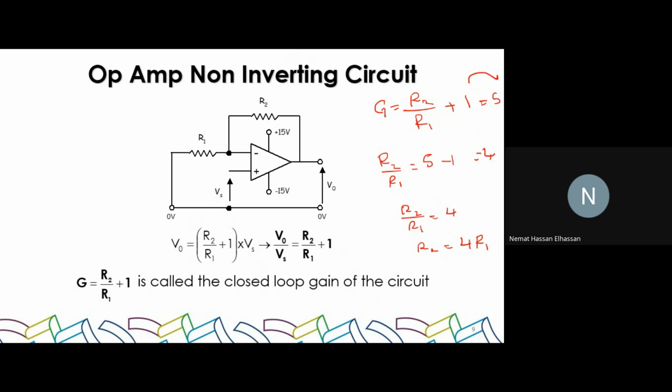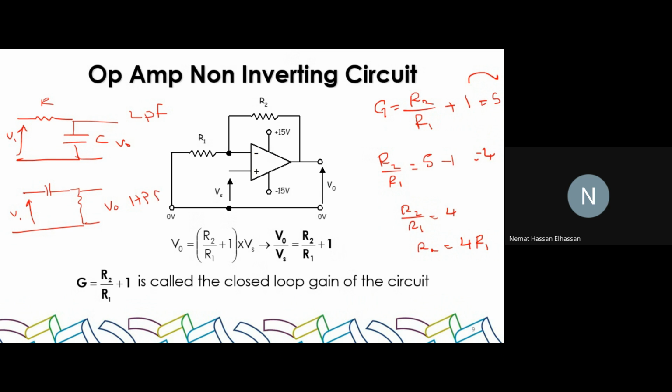Okay, I know that some of you didn't attend last week, so it will be difficult for them to pick up the filter. But just to help you along, let's remember that last week we learned how to build basic filters with resistors and capacitors only. This circuit with a resistor and the capacitor builds a low pass filter where this is the output and this is the input. If you take the exact same circuit but just replace the output terminals and say that the output is the voltage across the resistor, this will build a high pass filter.